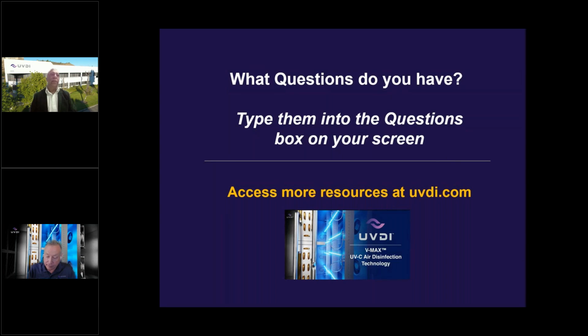But of course, for UV systems in air handlers, there are UL standards for electrical safety testing. It's UL 60335-2, the one that has been used to validate the electrical safety for UV systems. And 62471 is for your photobiological safety. There are a couple of standards for upper air, UL 8803 and 8802, which have just come out in the past year, which you can follow.